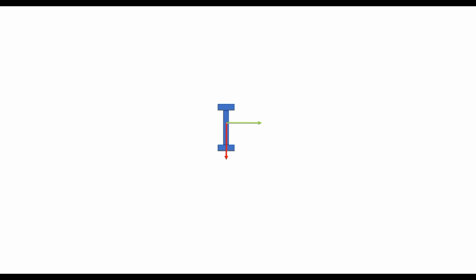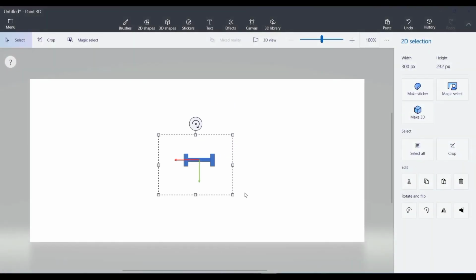Well, the non-zero beta angle specification is what would help us to achieve this in STAAD.Pro. Let us look into this concept further. Now let us consider this representation of the ISMB 600 section in its default beta angle 0 configuration. In this case, the local x-axis is coming out of the page towards you, and hence we have the beta 0 default configuration of the local y and the local z-axis as you see on the screen.